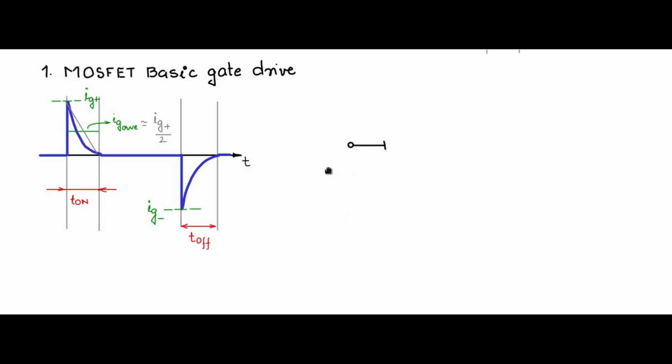So now let us draw the gate drive circuit. You have the Vg, the gate pulse, being given at this point. Then you pass it through a resistor and connect it to the gate of the device. The drain of the device is connected to the external load, and it is the drain current that you want to switch on and off. And the source you connect to the ground. There is an internal equivalent capacitance which is going to absorb the charge that you pump in. We will call this Vg, and this is R1.